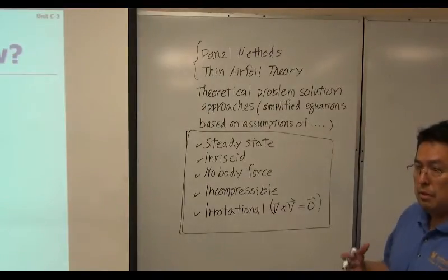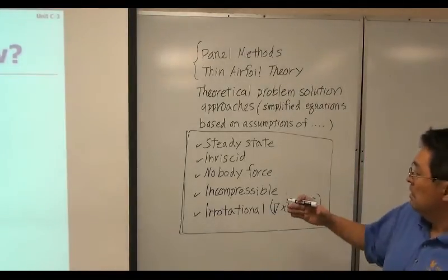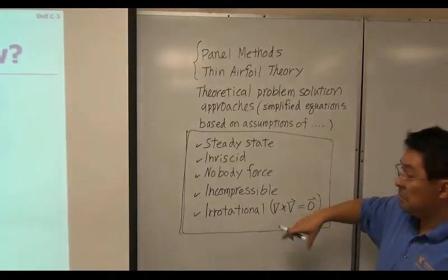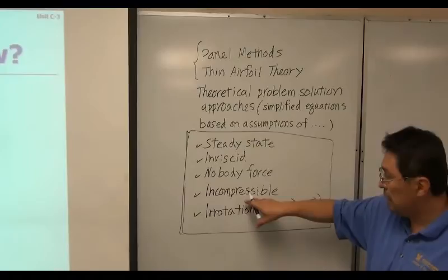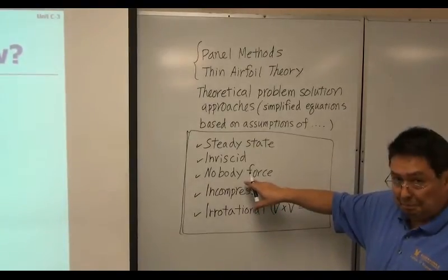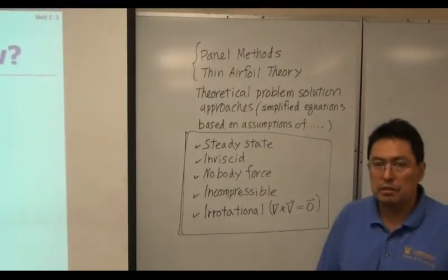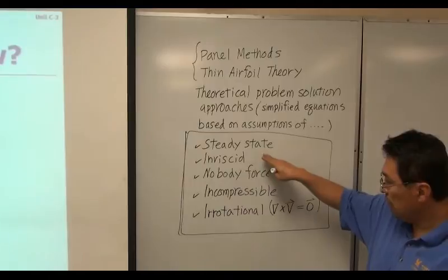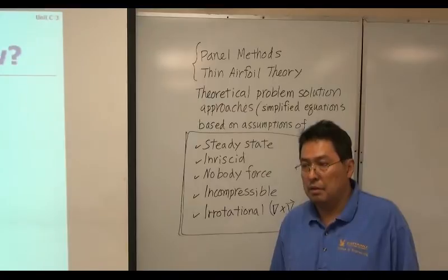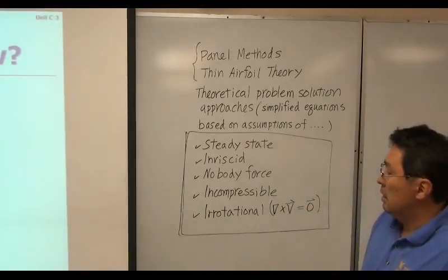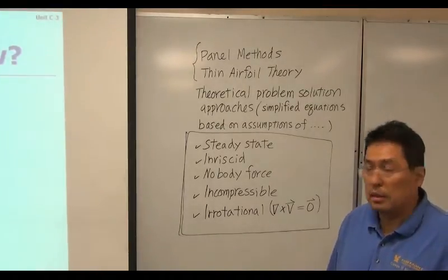If your results are not satisfactory, of course you're going to put those assumptions back into it. Let's include rotational effects. Let's include the change of density. Let's include gravity. Let's include viscosity. Let's not even assume steady state. So you can put those assumptions back on, layer by layer, if necessary. You can build a more accurate analysis later on.